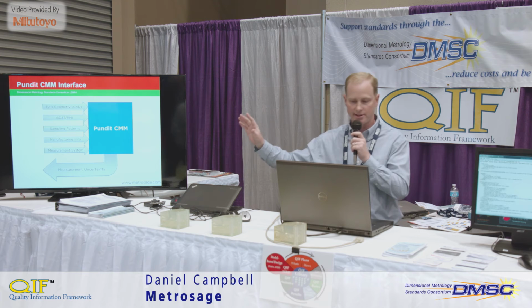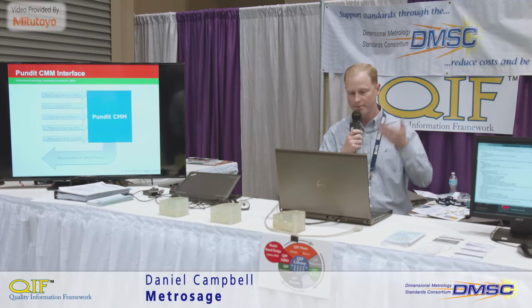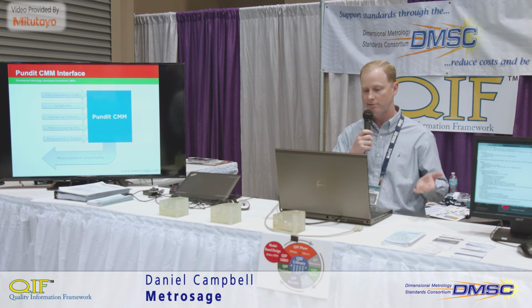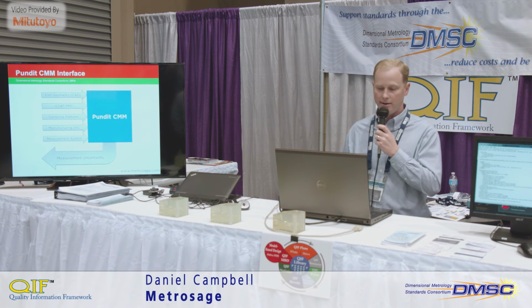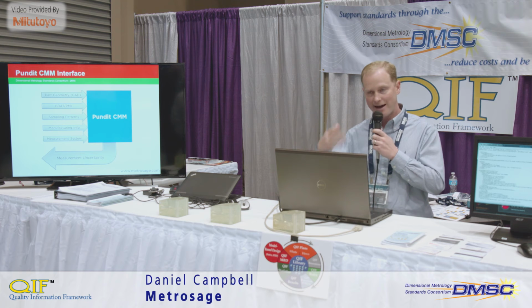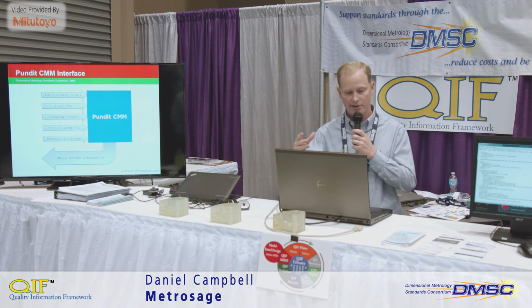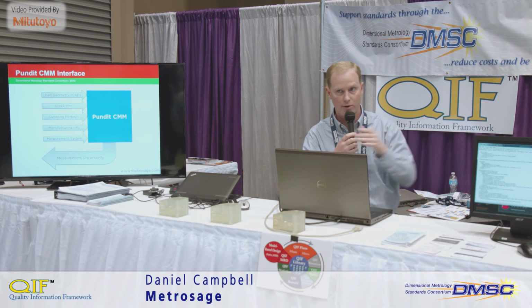Here are the inputs and the output from our Pundit CMM technology. The output, obviously, is the measurement uncertainty. And inputs, we require information about the feature geometry, information about the GD&T or the tolerances that are applied to each of the features, information about the sampling patterns that will be taken by the CMM, some information about any manufacturing error signatures that might exist on any of the features, and finally, the measurement system that you're going to be using, what measurement equipment.